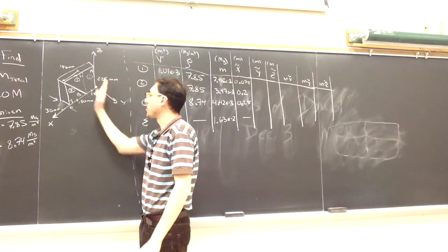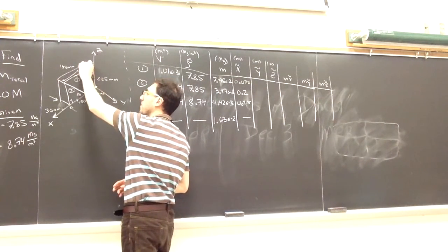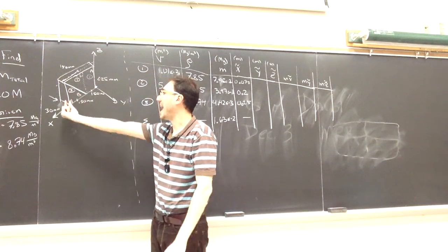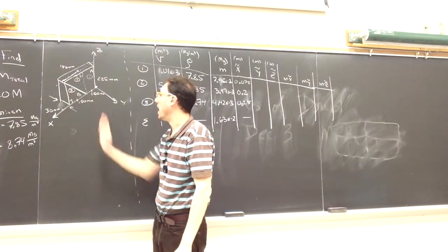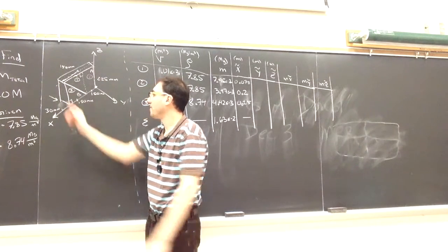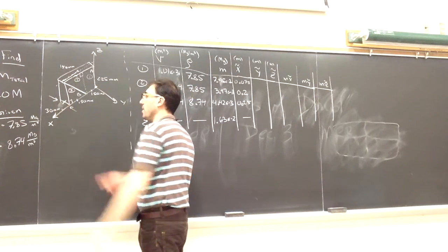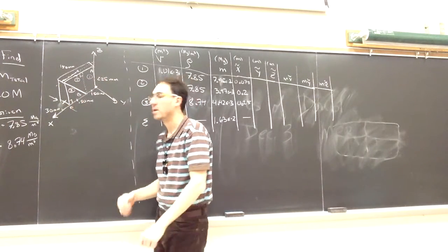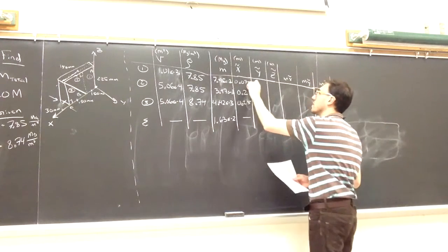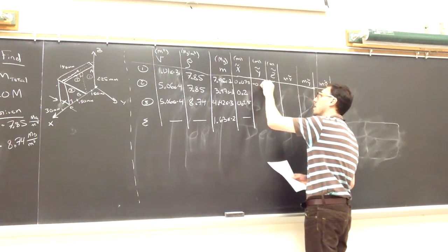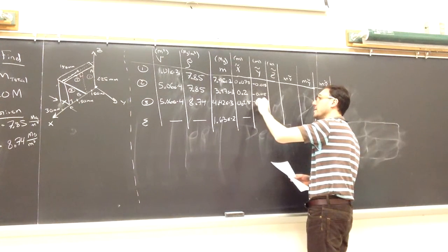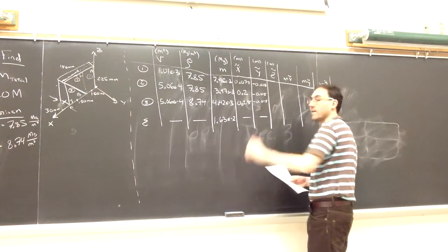In the y direction, this one's actually pretty simple because they have uniform thickness here. Each one of these shapes is going to be half of its thickness, but in the negative y direction. So 30 millimeters, half of that is going to get me the y centroid for all three of my shapes. So 15 millimeters or 0.015, and it's negative because it's in the negative y direction.